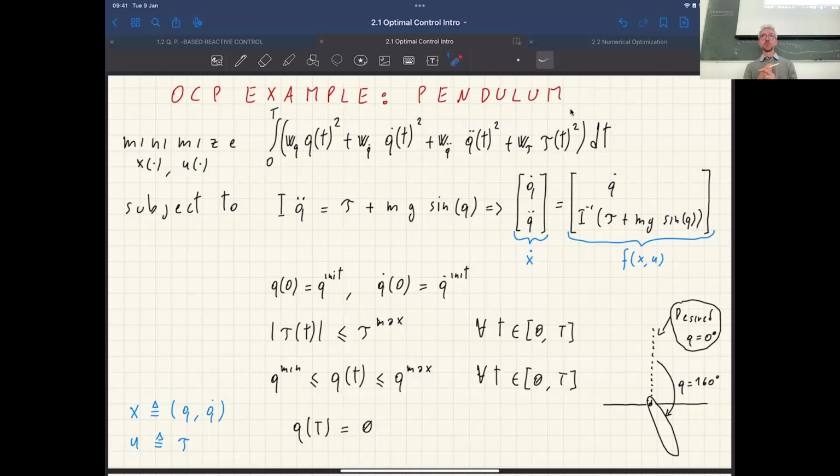Maybe that's not trivial, but typically when you minimize the square of a quantity, which is a trajectory, that also has the effect of smoothing it out. It's not only going to reduce the peaks, but it's also going to make it smoother, which is very good for robotics. This, of course, is going to have the effect of making the joint trajectory a bit slower, because if you're minimizing velocities, it's going to be slower.